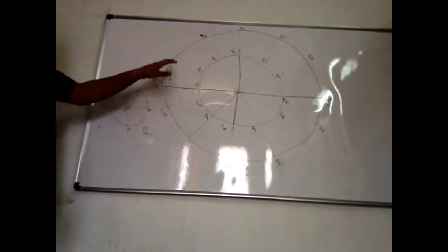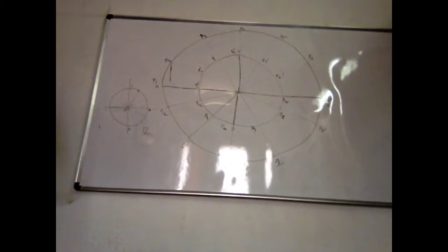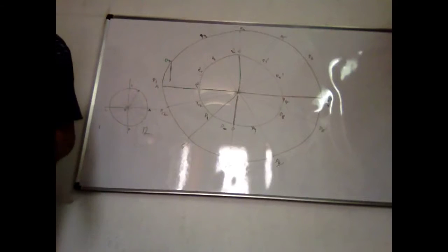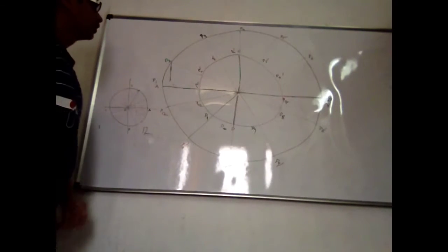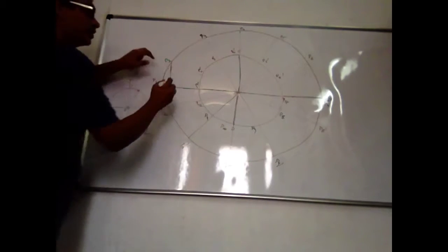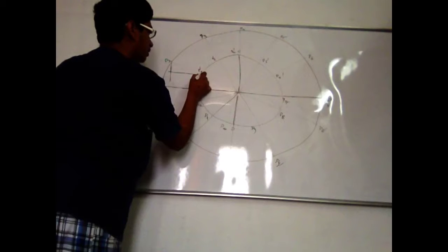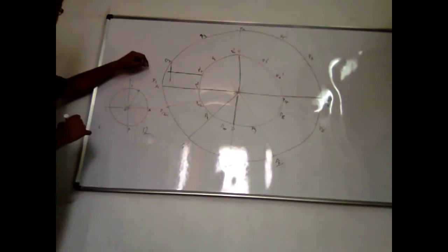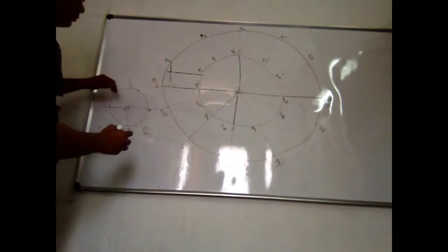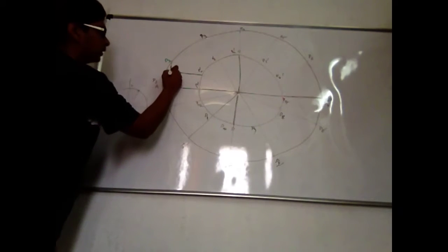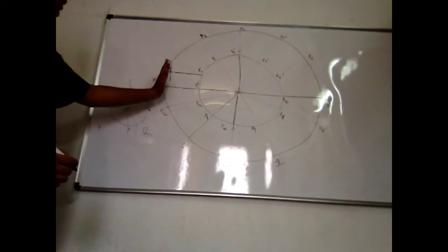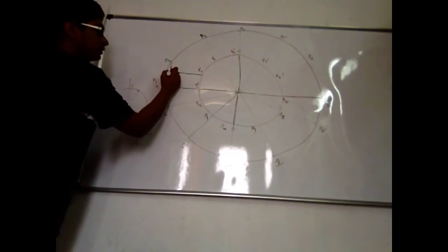So now you have marked the points, marking with an HB pencil. Good. Now what you need to do is draw a horizontal line through this P2 dash, which meets the vertical line from P2, and mark that intersection.